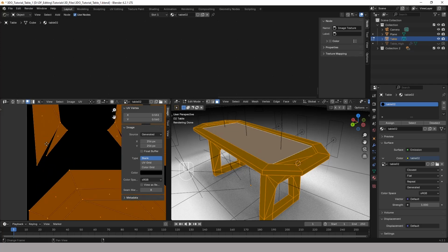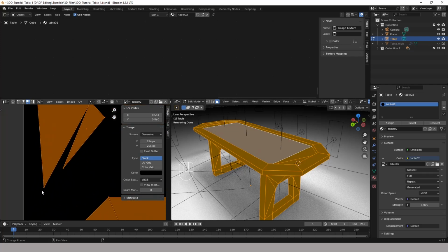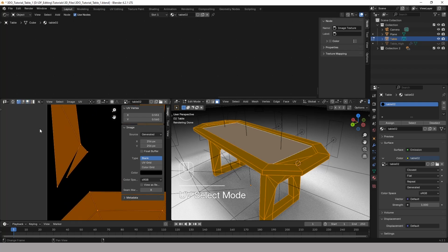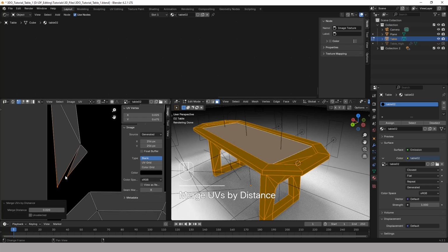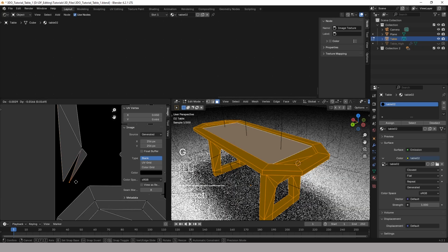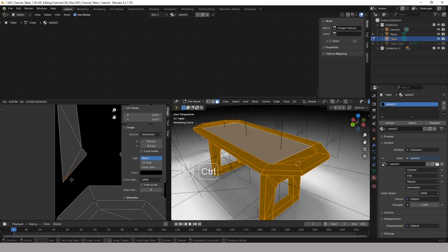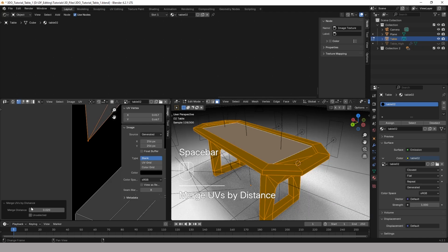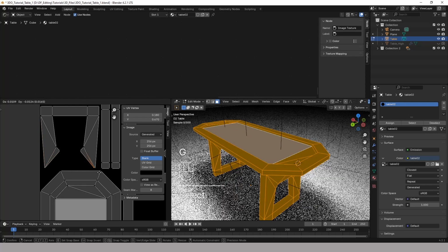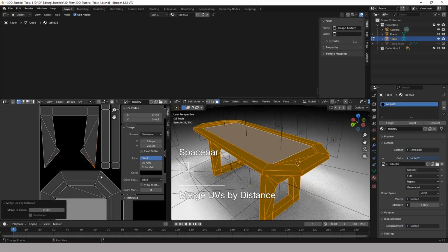The other thing you'll notice is because I had this UV mapped earlier, and we adjusted merging those vertices, this now no longer aligns. However, what you can do is basically the same thing in the UV unwrap. So, merge by distance, that's not going to work there, but I can control snap it to where it was. Merge by distance. If we just bump this up to 0.1, just to make sure that's going to work. So G for grab, move it close, merge by distance.